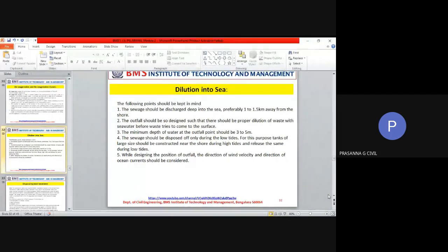Fresh sewage, septic sewage. So when your wastewater is fresh, you opt for dilution in water. And where floating matter, large floating matter, is removed from the wastewater before you dump it into the sea or other natural water bodies. And where the wastewater volume is very small in comparison to the quantity of water available in your disposal waters.